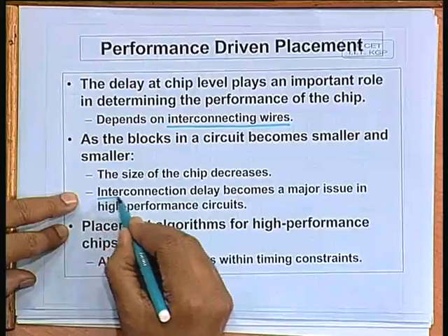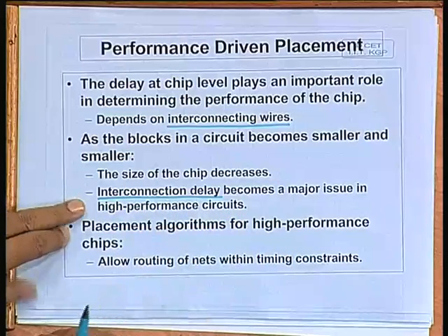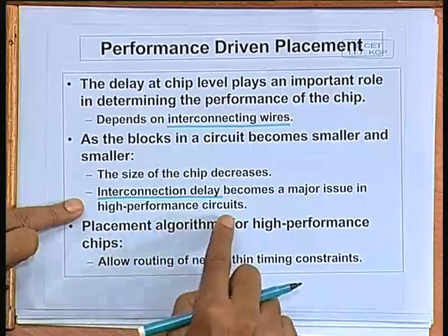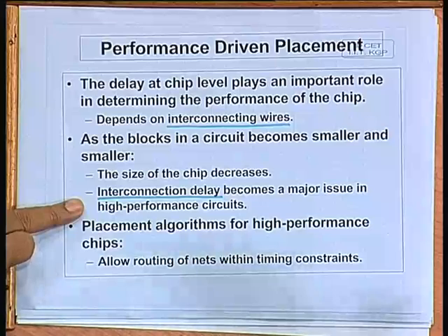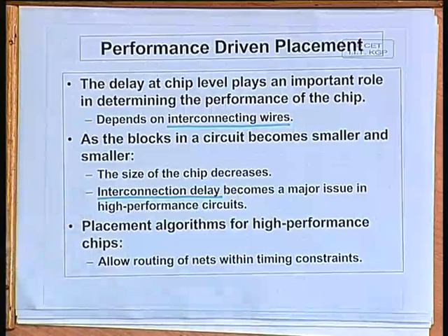So, finally, it will be the interconnections which will be dictating the final speed of the chip, like how fast the chip will work. So, interconnection delay has become a major issue if you want to make a circuit which will be running as fast as you want.